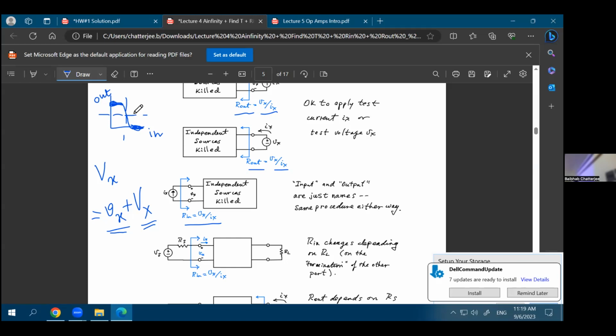So this might be a little confusing at first, but I just wanted to mention this so that you remember that whenever we do AC analysis, and that will be like 10 lectures away from now, don't worry about this right now. But during those analyses, we'll consider this also as ground, AC ground, or a virtual ground. It's not a real ground, it's not 0 volt. That's why it's just an AC ground, which effectively means that there is no AC potential here. Right? Agreed? There is no AC potential in your supply, which means the supply is also an AC ground. It could be confusing at first, but when we solve the actual problems, it will become much clearer.